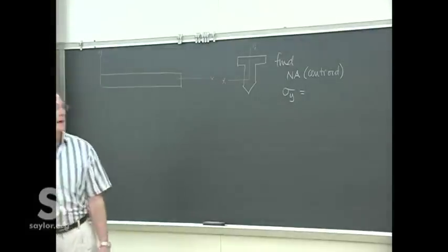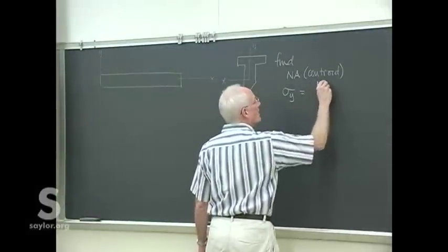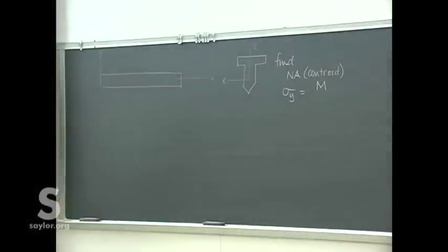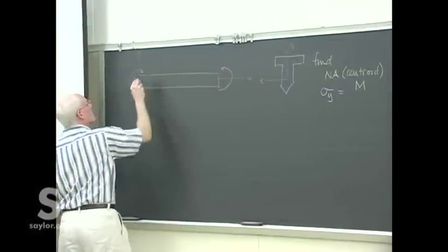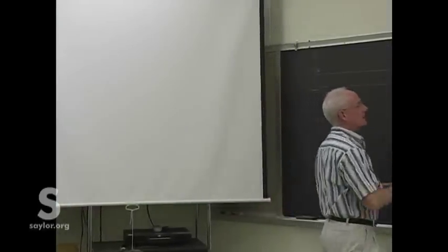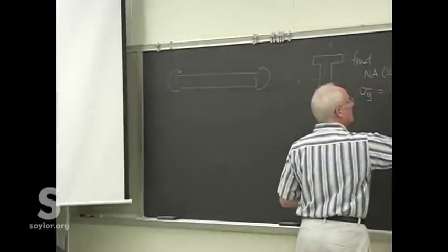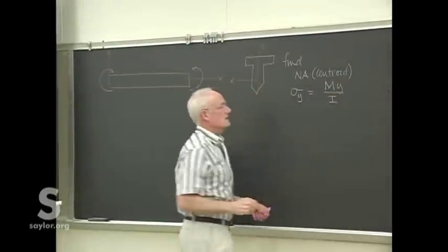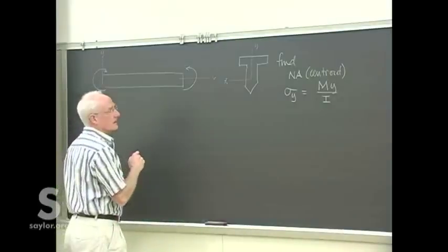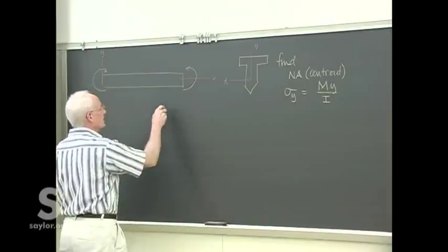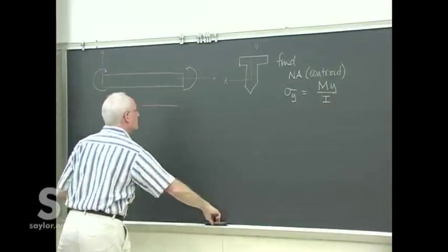because the stress as a function of y, if you remember, was whatever moment is being imposed. And there's another one of our restrictions. The moments must be in the z direction. Remember, using the right-hand rule, that gives us a moment that's purely in the z direction. And then we found that the stress was a function of that moment, the position across the cross-section, and then the moment of inertia, area moment of inertia.